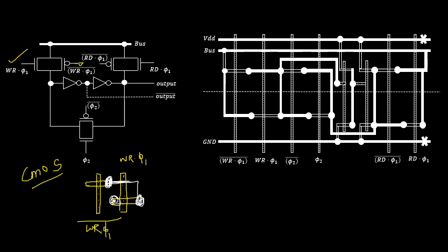So this is one connection. Another is, use a contact cut over here, use a metal layer, use a contact cut over the other end and make a metal connection like this. So this is the parallel connection. So that's what you can see I have done everywhere. So this kind of connection has to be repeated 2 more times. So in total it should be thrice.